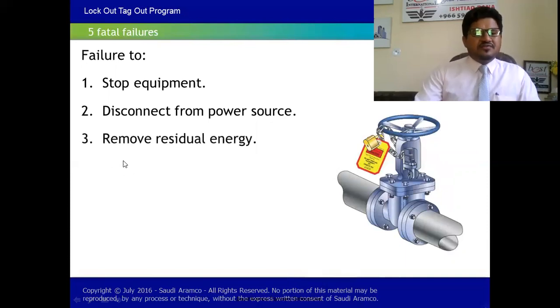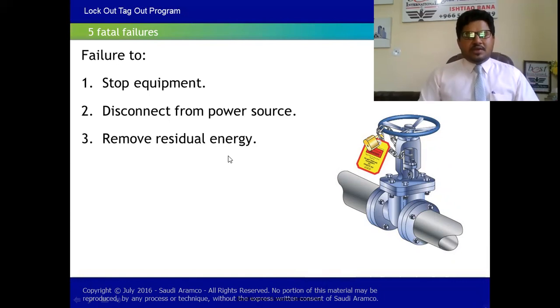Now, the third fatal failure is remove residual energy, the remaining energy. Like you thought the hazardous materials are drained out, or you thought the electrical and mechanical energy is fully locked out, but unfortunately hydraulic and pneumatic pressure energies are still there. And you believe 98% of the energy is already removed, so 2% will not create any harm.